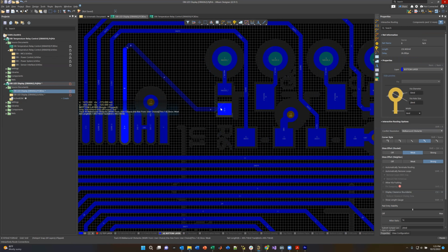It tells you everything that's going to do. It's going to remove this net, do this, do that, and the other. You're going to click execute. It does all the changes. You close, and actually now you'll notice that this pin is now ground. So that is completed.